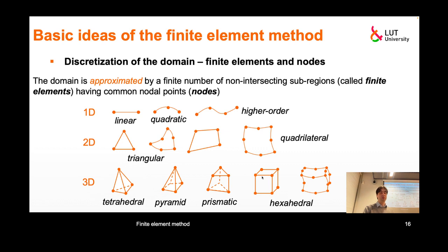And to connect one to the other, you can see that they are not directly compatible. We mentioned in the beginning that finite elements must share nodes, and it wasn't written there, but it's assumed that they must also share boundaries, shared faces. And they're not compatible. This one only has triangular faces, and this one only has rectangular faces. But we could make a transition from one to another using pyramid elements, which have both triangular and quadrilateral faces.